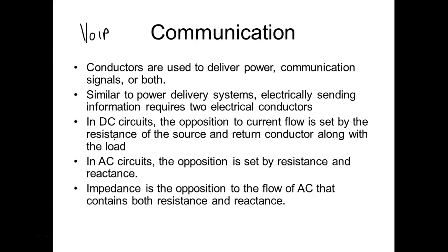What they did here at the college is they actually used 2 of the conductors in the network cable to power the phones up. But if I was to run it through a switch, then my phone wouldn't work unless we had an external power port.